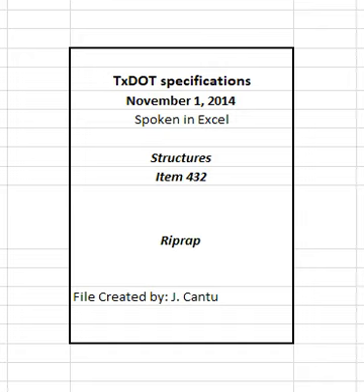2.5 Special riprap. Furnish materials for special riprap according to the plans. 3. Construction. Dress slopes and protected areas to the line and grade shown on the plans before the placement of riprap. Place riprap and toe walls according to details and dimensions shown on the plans or as directed.